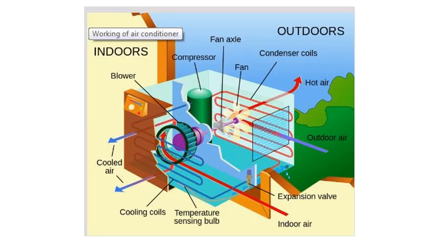to liquid state. Now the refrigerant in the evaporator coil, which was in liquid form, has been converted into vapor form, but it has low temperature and pressure, so it is sent into the compressor, which is present in the outdoor unit. The work of the compressor is to convert this low pressure and low temperature vapor form refrigerant into high pressure and high temperature refrigerant, which is also coming out of the compressor in vapor form.